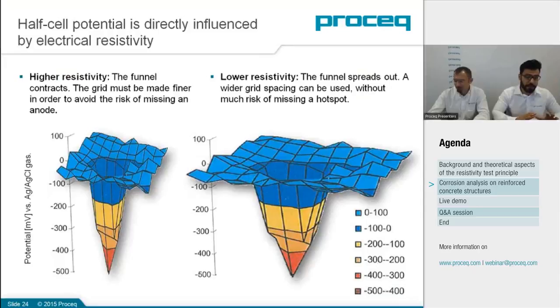But Guido is going to break it down for us in more detail, and this will talk about some of the recommendations that help us even further. And again, the design of the testing campaign is the critical starting point. In this phase, we're just optimizing the half cell potential grid.